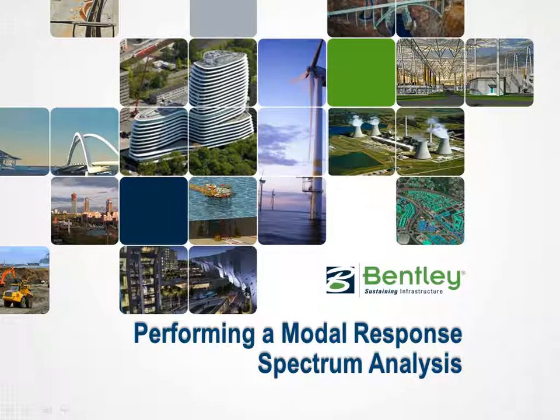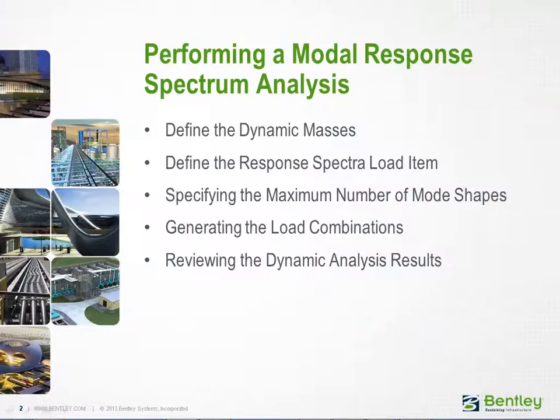Welcome to the Bentley Institute's training course to learn how to perform a modal response spectrum analysis in STAAD.Pro. A modal response spectrum analysis is a more elaborate type of seismic analysis. Response spectra are plots of maximum response, either acceleration or displacement, of single degree of freedom systems subject to specific excitation.